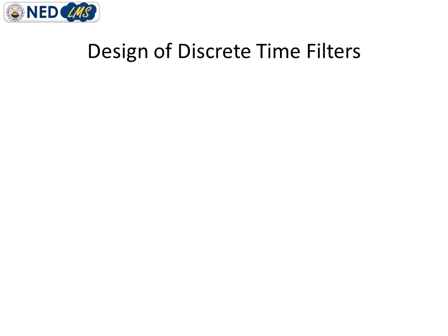So the first step to start the design procedure is the determination of the desired frequency response, that is, which response we are actually going to obtain from this type of system. After selecting the frequency response, we have to calculate the filter coefficients that will give us that response.